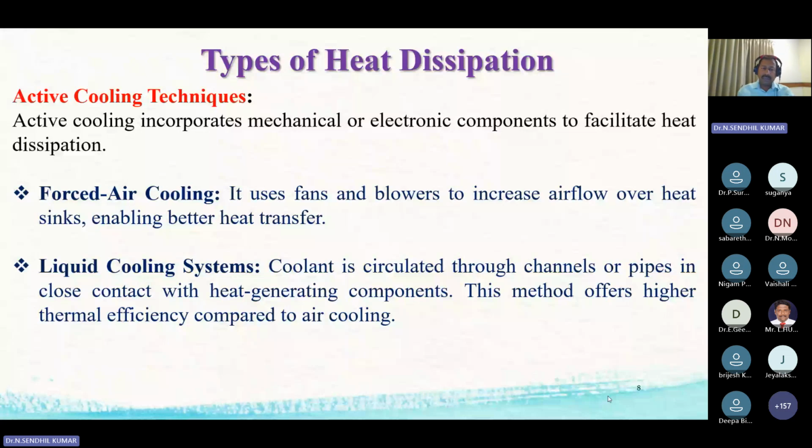The next is the liquid cooling system. Liquid cooling system means some channels and some pipes will be there. In that we have to circulate the coolant. What is the property of the coolant? While going, it takes the heat. While coming back, it delivers the heat to other places. So that is called a liquid cooling system.